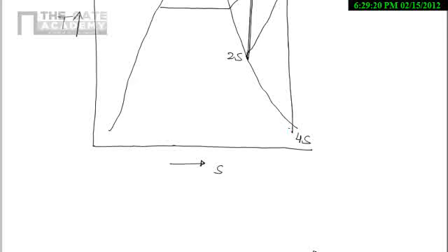So now from 4s it will pass into the condenser, so it will leave at this point, suppose 5, and 5 to 6s is nothing but our pump work, and again it will be heated in that process. So we are having these processes. This one is the cycle for reheating.